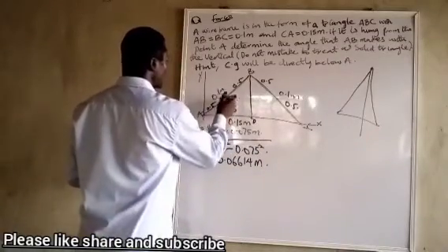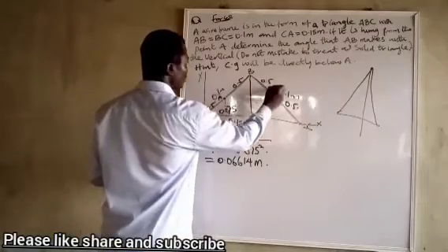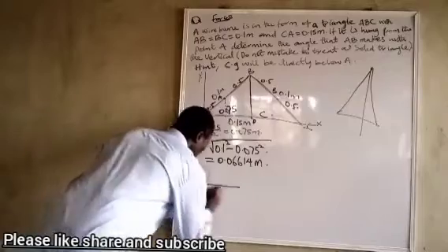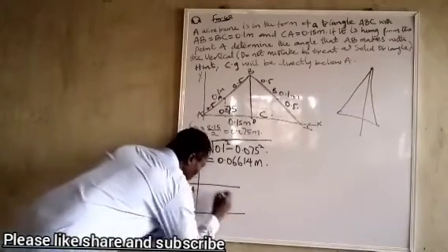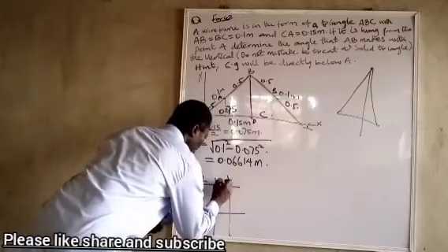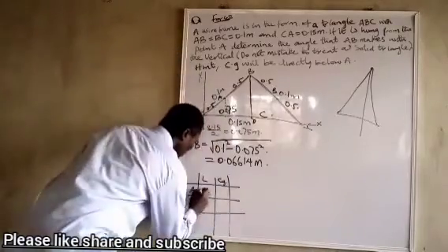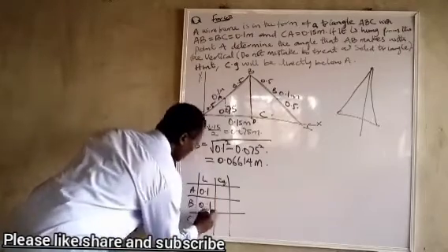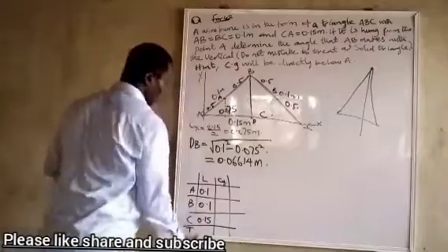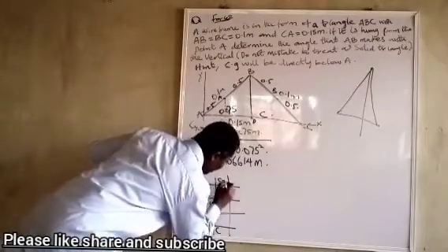Therefore, the moment of this area about this place, we are going to take it. So let's call this one A, let's call this one B, and let's call this one C. For A, B, and C, length y, cy. This one is 0.1. This one too is 0.1. And this one too is 0.15. And then we have the total there. You get it. 0.35. Fine. So this is our CG, CGY.